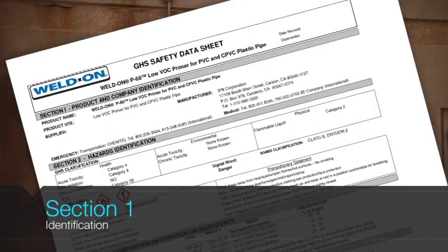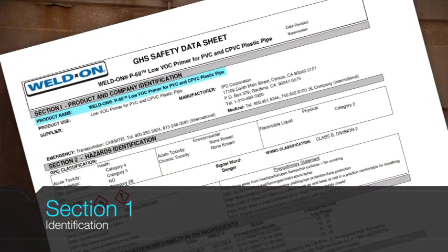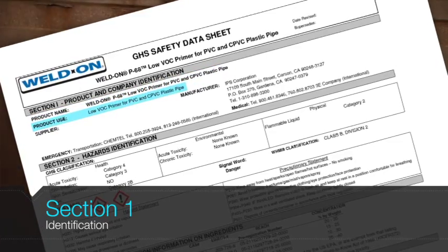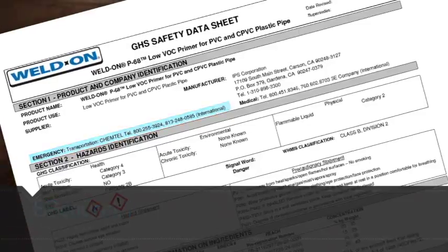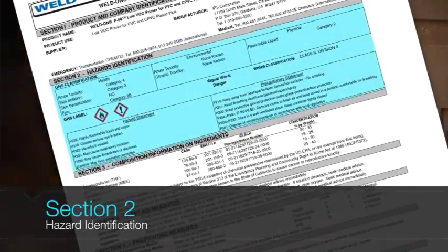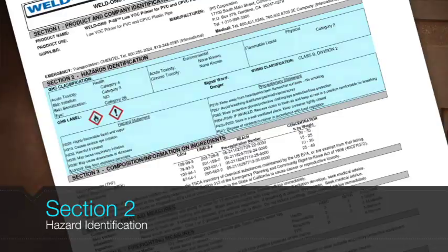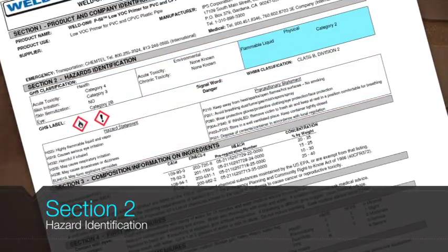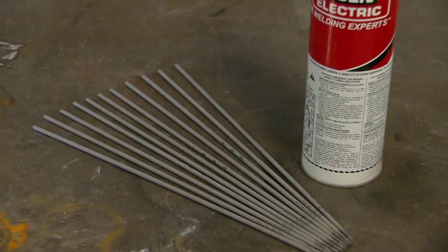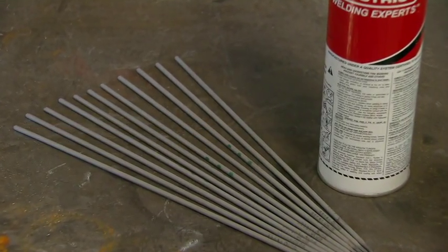The new SDS is divided into 16 sections, but you won't need to reference all of them. Section 1, Identification. This is where you find the product identifier, recommended use, contact information, and an emergency phone number. Section 2, Hazard Identification. This section requires a more detailed explanation. In it, you'll find that the chemical is classified according to the nature of the physical hazards, such as a flammable solid, or health hazards, such as a respiratory sensitizer.